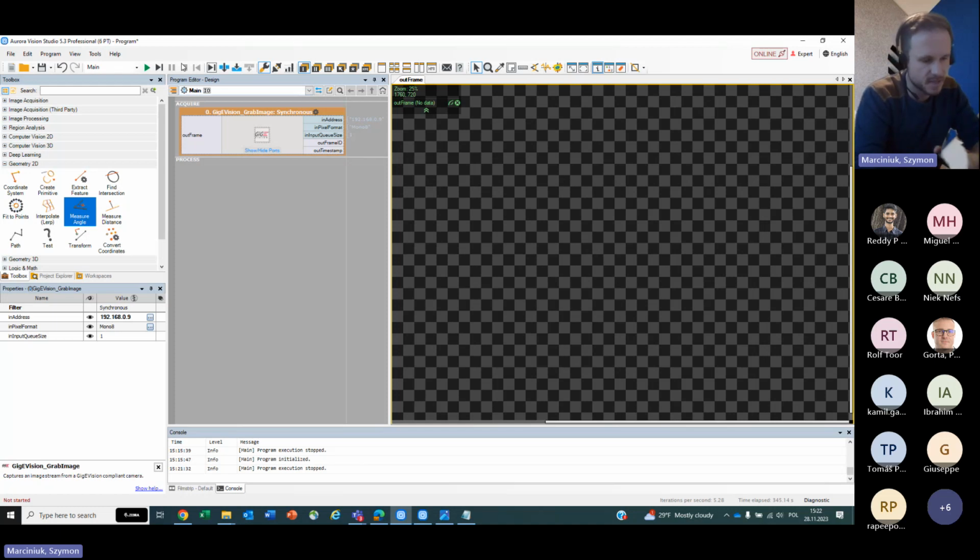The first step, calibrating intrinsic parameters, is about calibrating lens distortion, calibrating everything that is related to the camera as a device itself, and it can be done even in a different place. The camera doesn't have to be mounted on the actual working station.